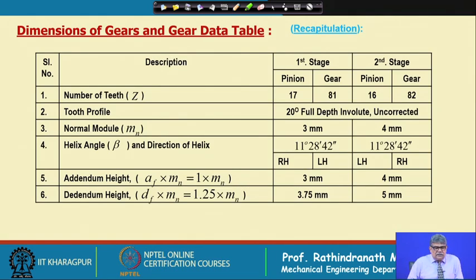And this again is the problem. Just to mention that it is of around 24.5 reduction ratio, second stage around 5.2, and first stage the rest of the part, 4 point something in the first stage. And in the last stage we have module 4 millimeter, and the gear dimensions we have already discussed many times.